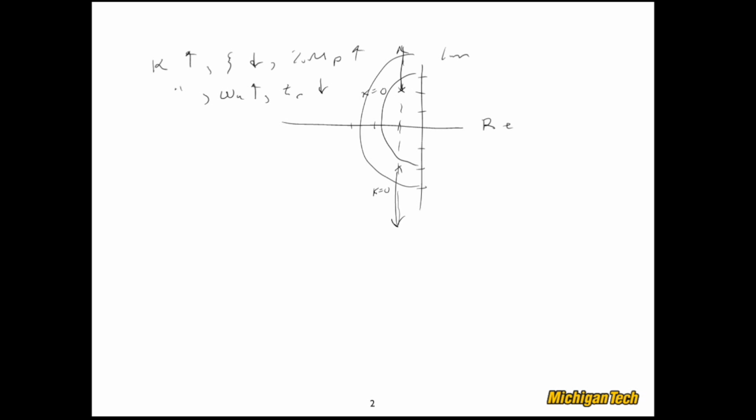So now let's go ahead and do a lead compensator design. And the goal is going to be to try to keep the percent overshoot about what it is now. And so the way I'll approach that is trying to keep zeta approximately what it is right now, but achieve some faster response, increase omega n. I can't do that now because if I tried to increase omega n, my zeta would go down.